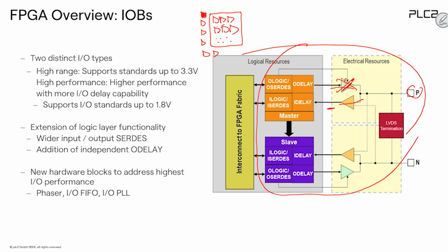And then just some information. We do have also some kind of complexity inside every cell. We have some very special logic which allows us, if there's an input, to delay an incoming signal. So I have an input, but maybe for some reason I would like to delay it by, I don't know, 100 picoseconds in order to fine tune high-speed data transmission. I can do this, or I would like to register this inside the cell, not just running with a high-speed net, but internally, just do the registering inside the cell.